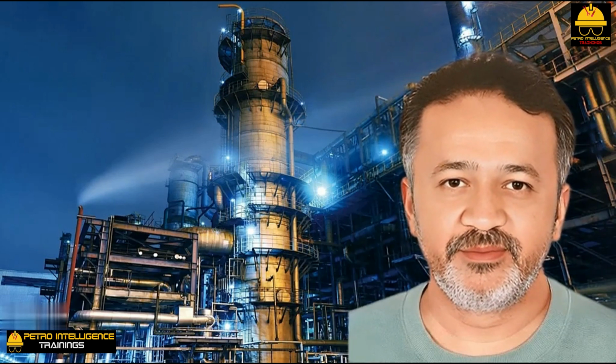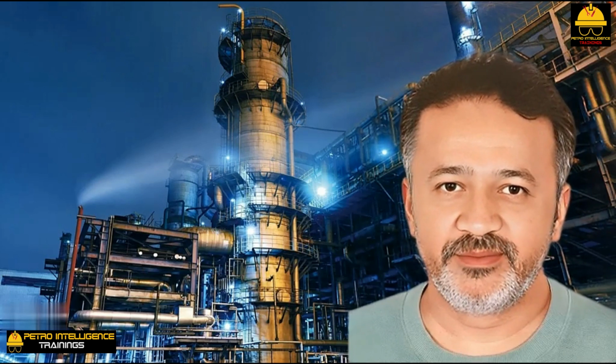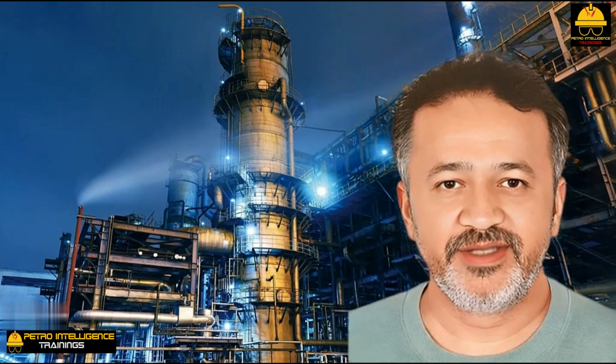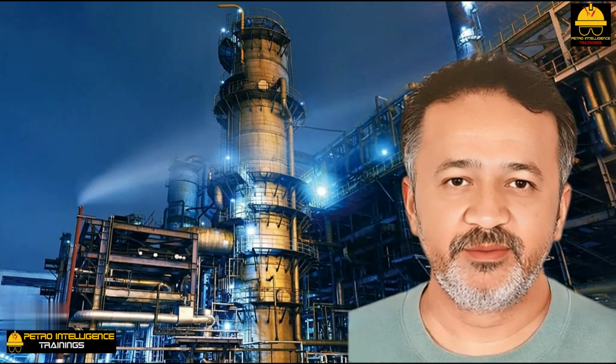Tower pressure control. For total condensers, there are three general schemes for controlling distillation tower pressure. Throttling the cooling water flow to the condenser. Flooding the condenser. Hot vapor bypass around the condenser. Regardless of the method selected, the principal concept of tower pressure control is the same. We control the pressure in the reflux drum by manipulating the temperature in the reflux drum. The tower pressure then floats on the reflux drum pressure.